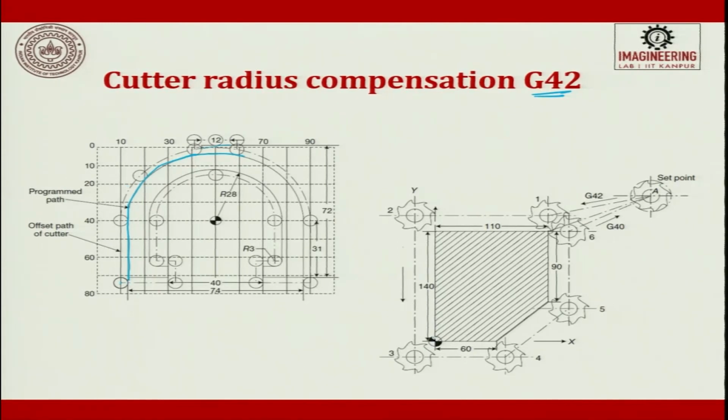When you look at it, this is the center, and here is your first point. The cutter comes in contact with the workpiece and starts cutting. From here the center is moved here, and this is your offset diameter. If it stops exactly here, it will try to cut inside the material. In order to avoid this, we offset by half of the diameter, move to the extreme out, so the tip must touch here. The center must be shifted.